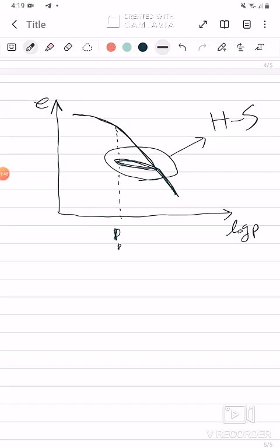As we can see, the hardening soil model has some main advantages over Mohr-Coulomb. So usually in modeling with Plaxis, it is preferred to Mohr-Coulomb. But there is a significant problem. Although the behavior of these two models before reaching the failure line is totally different, in the failure situation, both of them follow the Mohr-Coulomb criterion.